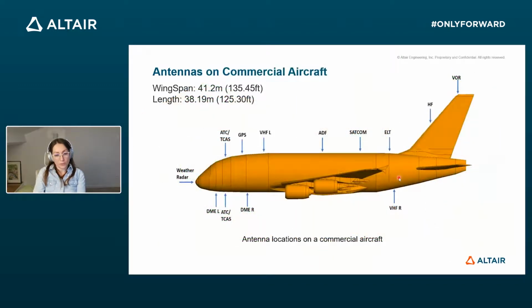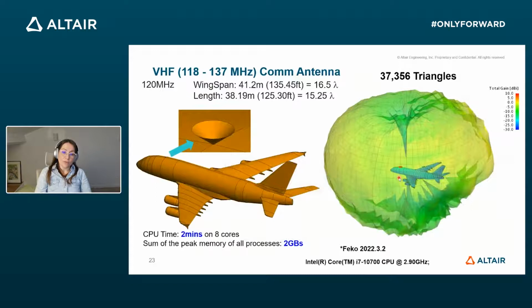So another type of problems is that when you have multiple antennas that you need to place on one platform, and in this case, each antenna performs in a different communication system and at a different frequency. So one issue is that you need to perform some analysis for placing these antennas and to analyze the mutual interference effect between these different antennas. So in order to do that, you can perform different runs and different simulations for each antenna separately, and then analyze the interference effect.